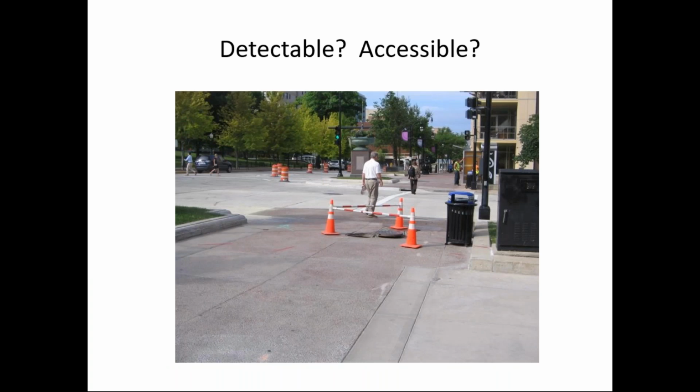Then how about this? This is more of a short-term project, probably on the order of an hour or two. You can see here they've taken the manhole cover off, and I was here for about 15 minutes. There are two individuals down there below grade, and most of the time I was here, a third individual was standing here as a spotter. I don't know what happened, but I turned around and he was gone. So this is not a good situation to have that open side there where someone can walk into that.